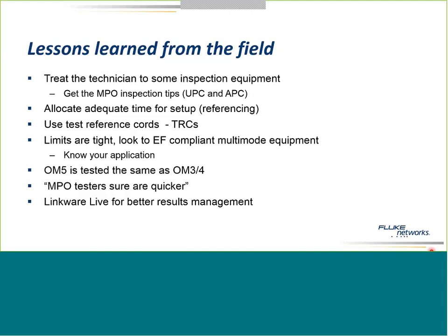Here's a fun question. I'm using OM3 test reference cords. Can I test OM4 cable? Yeah, if your test reference cords are OM3, go ahead and use them on OM3, on OM4, even OM5.